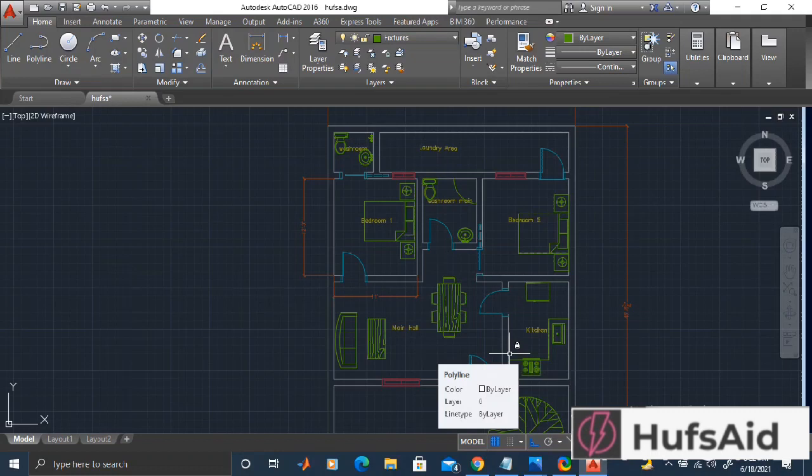the reflected ceiling plan. Let me simply explain what a reflected ceiling plan is. A reflected ceiling plan is simply, you will see this ceiling, you would see lights on the ceiling, like the position of lights. This position of lights is not decided by the electrical design engineer, but by the architect himself. So what an electrical design engineer does is he just places the lights of different wattages and tries to achieve a certain lighting level.